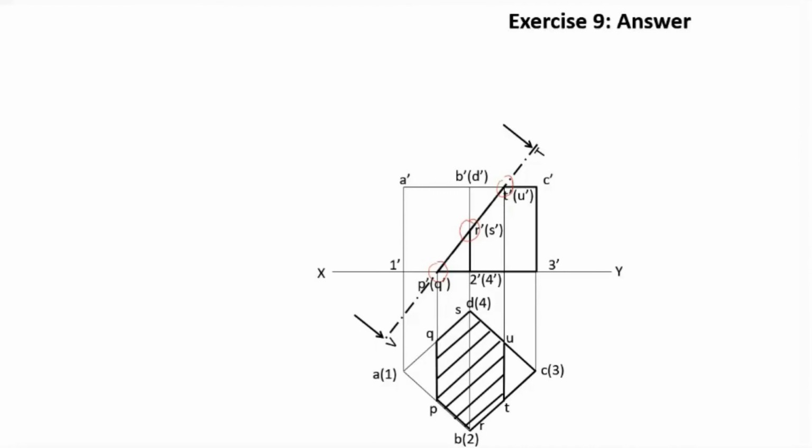Since this particular portion is removed, that portion is not drawn in the top view. That portion is removed, but this portion is remaining in the front view, that is within that particular section. So that portion is left out within our section, I mean the section sub-object.